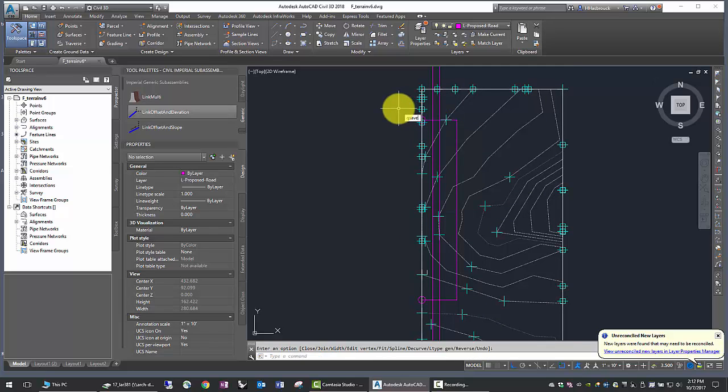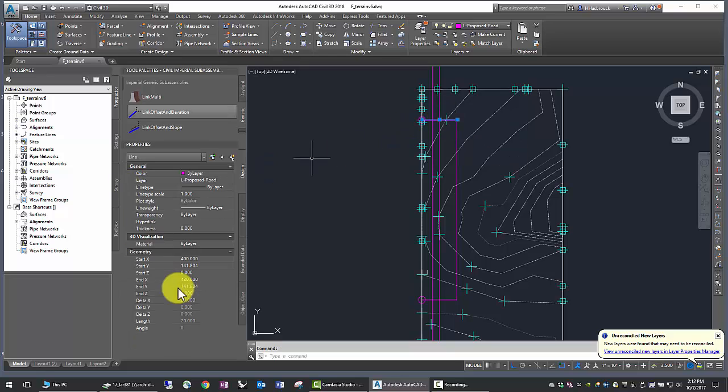Alright, so read the command prompt, 0 segments added. What that means is that they're all at different z heights because I snapped to a point that's on the boundary. So what I need to do is using the properties editor, check to see what the z heights are at the beginning and the end. There's the culprit, it's at 5. Turn it to 0.